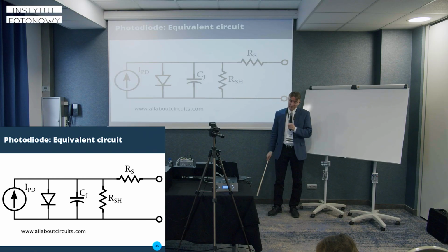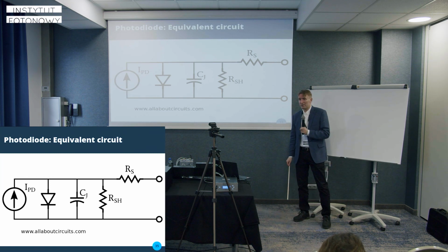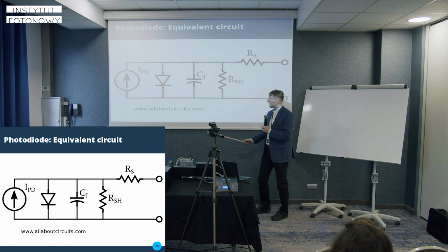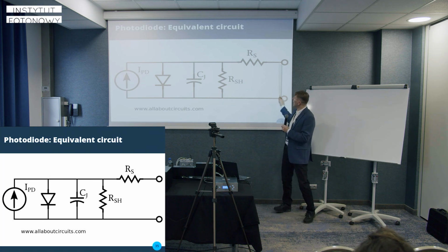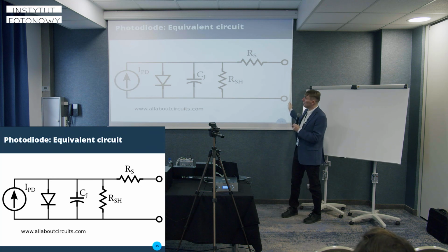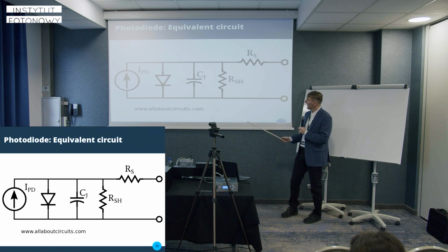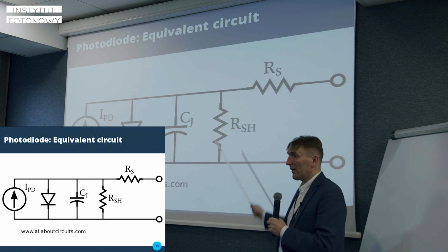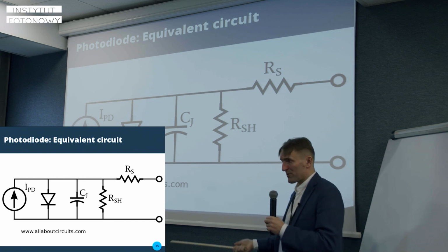And there is this shunt resistance, or parallel resistance, that you would like to have as big as possible, because it competes with your load. If you attach some load and you would like the photocurrent to do some work on the load, then this will short the circuit before, and some of the photocurrent will be diverted through that loop, which you may not want.